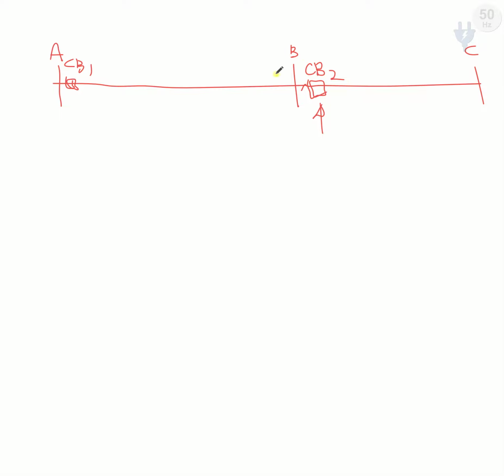During the opening of circuit breaker 2, the relay we installed for section AB thinks that there is a ground fault or a sensitive fault, because the CT and the PT are connected to this relay.